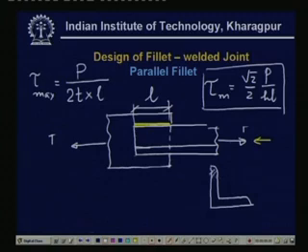So, this is the cross section of the plate. This plate cross section is here. We have the center of gravity somewhere here. So, this is the center of gravity, and now if you apply similar joints on both sides, again because of the asymmetry of the structure, there will be bending stress developed. So, we will have to make two different lanes of welding now.